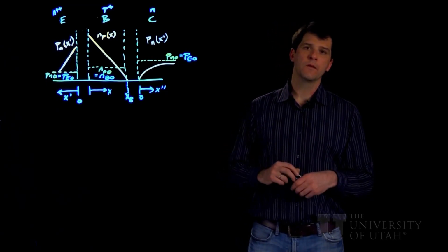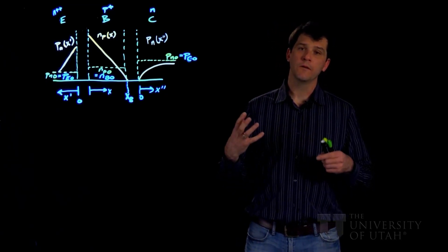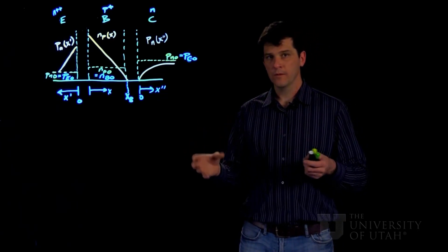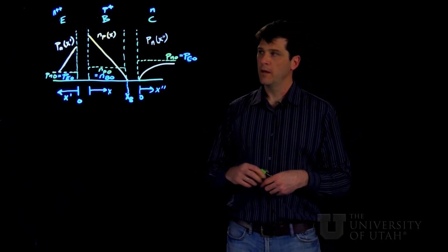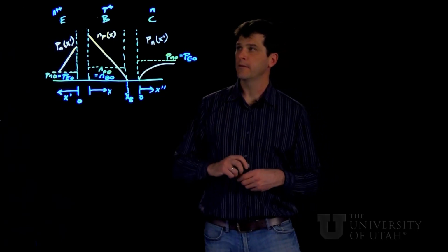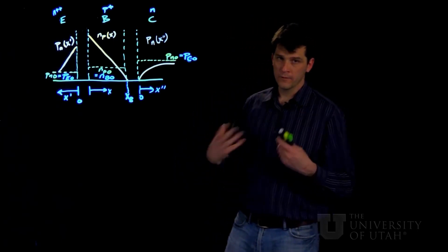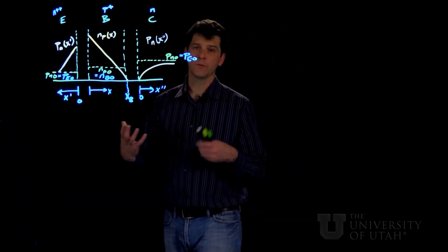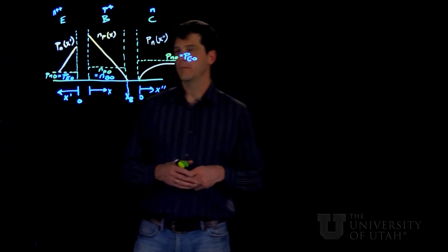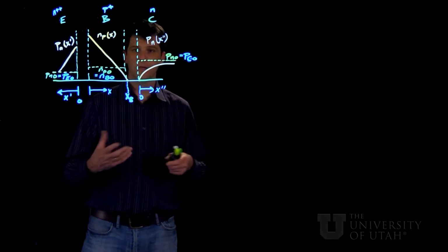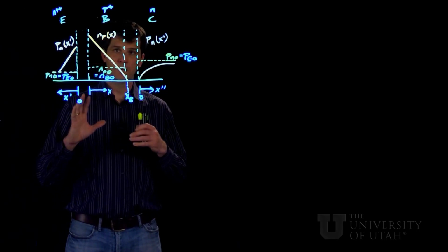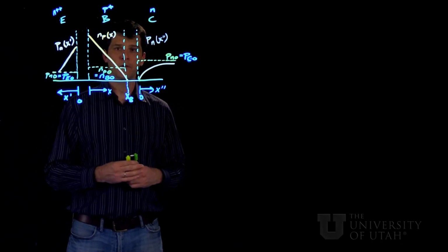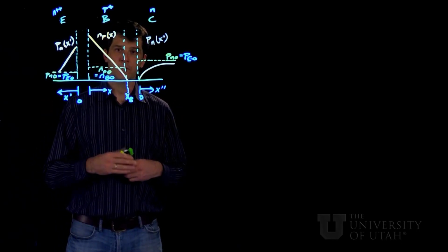And now let's look at the actual derivation of those currents and how those relate to the carrier densities inside the transistor, and thus we can actually derive formulas for the gains as a function of the doping and other parameters of the materials and, of course, of the voltages.